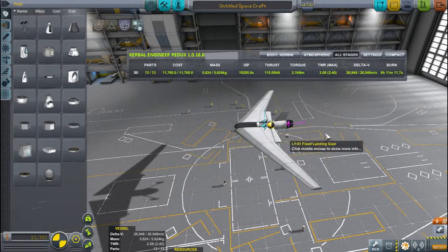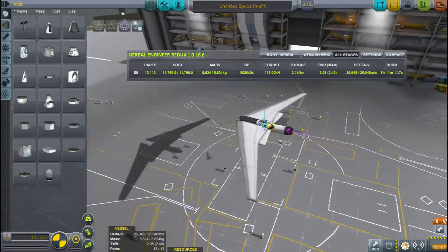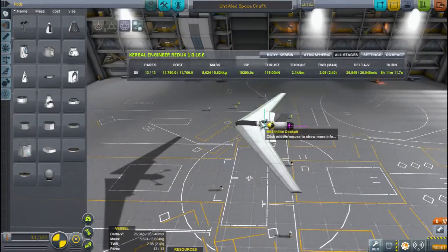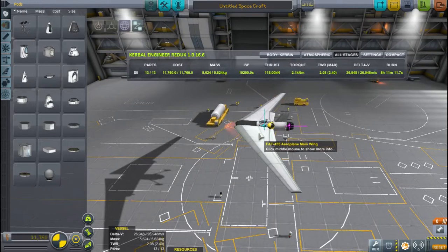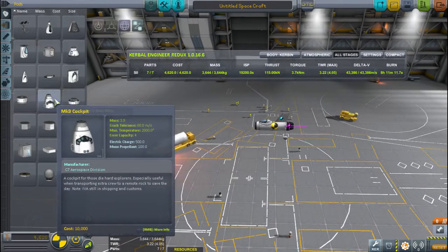This guy is a lever, and as you move through the air, you've got lift on the front of the craft, and that generates lift on this cockpit and pushes it up. So far so good, but the problem is once you pitch up, this guy will continue pushing back. So this thing is intrinsically unstable.